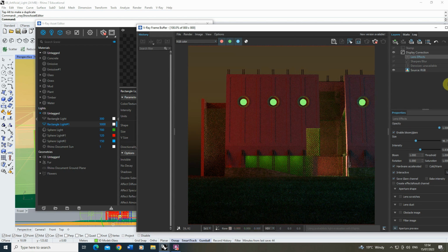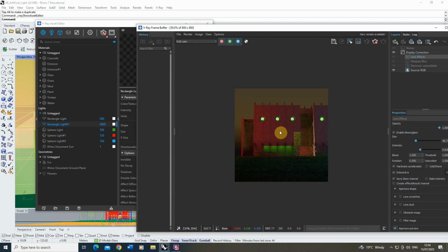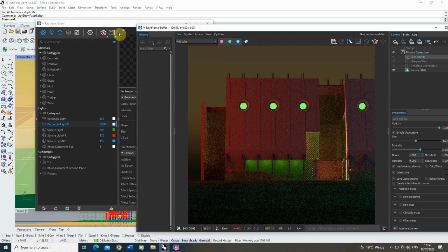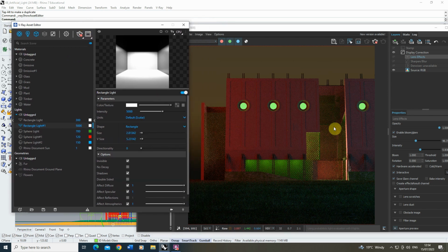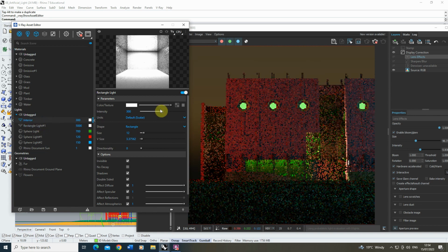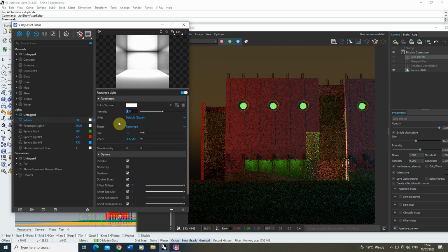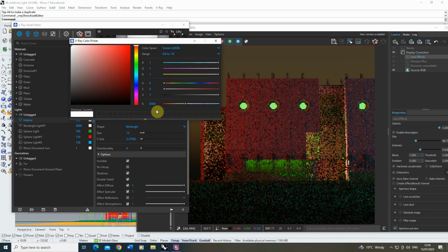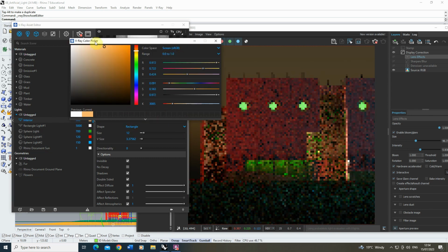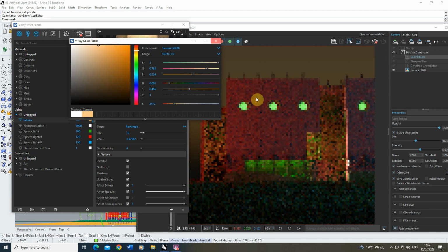The nice thing is, once you've made all of these lights, you can then just start to dial them in and out depending on the intensity you want of each one. So let's say we want the inner glow to be a bit more. I can go back to my inner lights, and we might want to rename these as interior or exterior. And we can start to adjust these. So maybe we want this to be brighter. Let's put it up to a 900, but also warmer. So I'm going to make it a little bit orangey there.